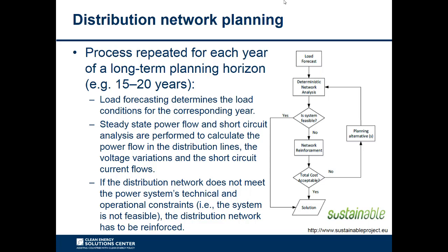Later, they are doing a deterministic network analysis. So basically, they conduct steady-state power flows and short-circuit analysis, which are performed to calculate the power flow in the distribution lines, the voltage variations, and also the short-circuit currents.